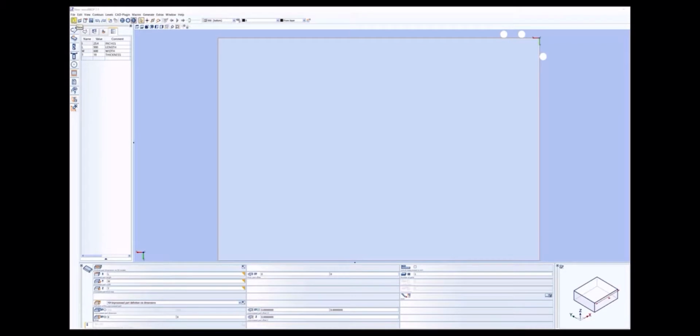Open up a new WoodWop file so you can create a pegboard using a block and vertical drilling operation. First thing we want to do is define our variables. Your inches will be 25.4. Your length and your width will both be 800 millimeters. Your thickness will be 6.35 millimeters. And then create a variable for grid X, which is GX of 32 millimeters, and a grid matrix named GY of 32 millimeters.